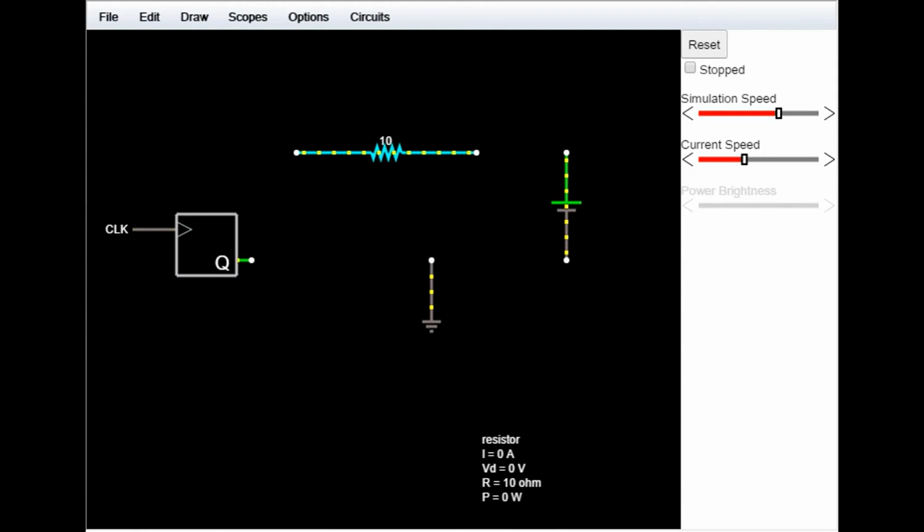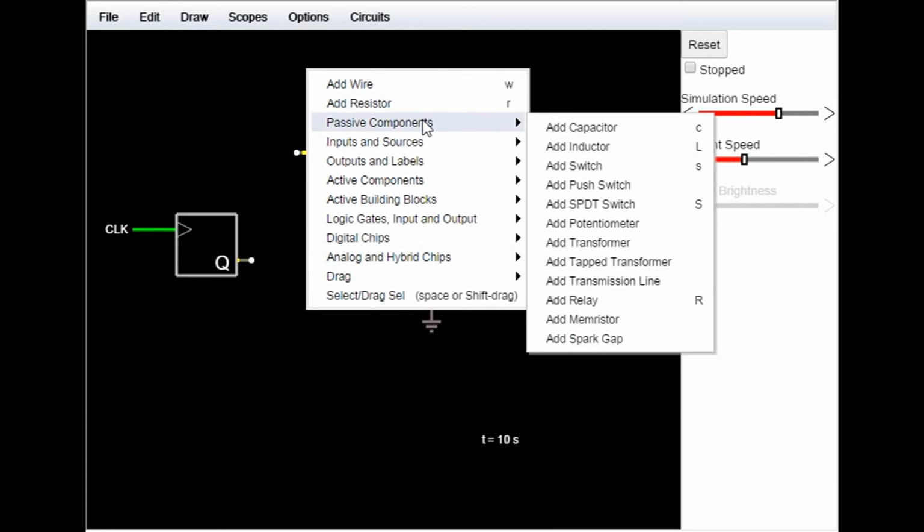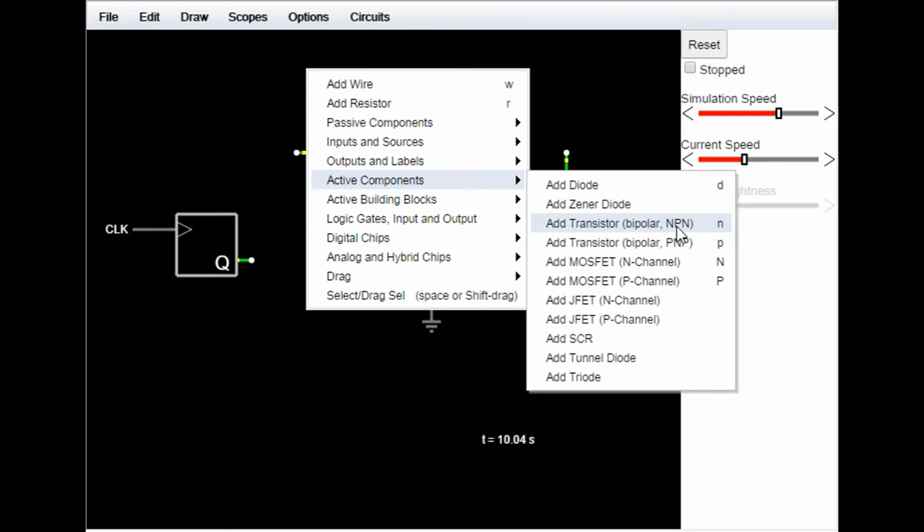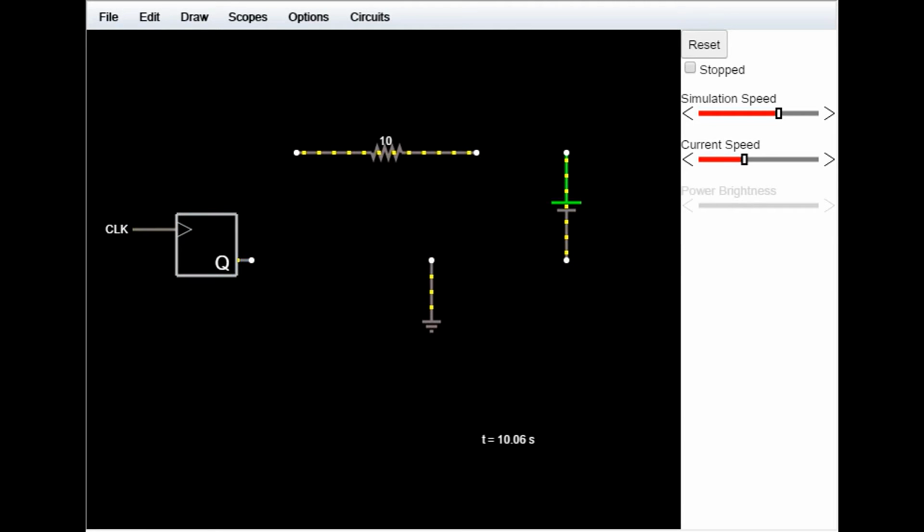No, in order to drive a motor, you need to use a driving transistor. So let's add a transistor to the equation. We've got our NPN BJT transistor here. The way I'm going to arrange this is so that we're going to have a high volt line coming out of our 12 volt battery. Let's move this here.